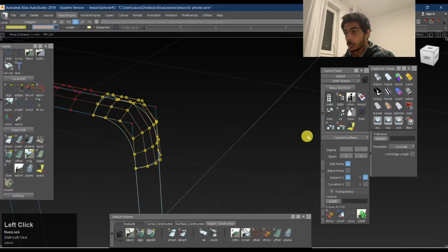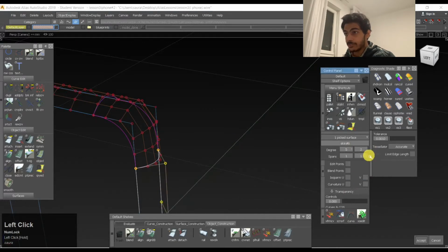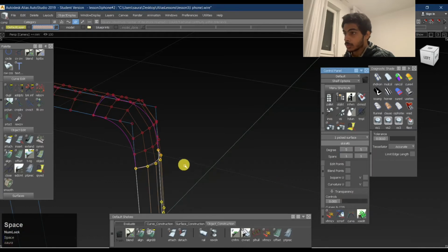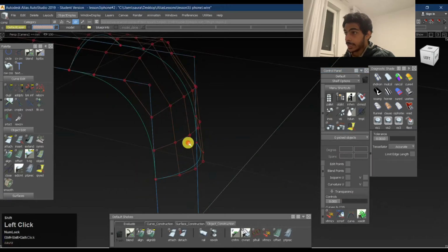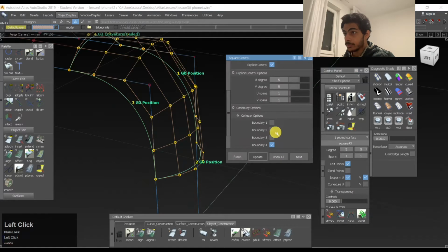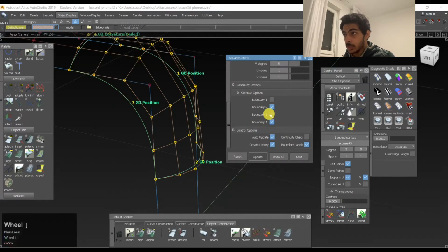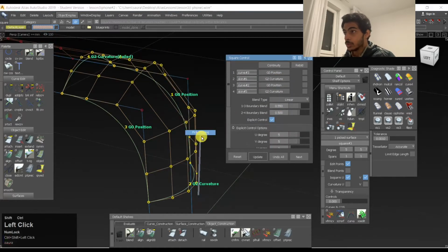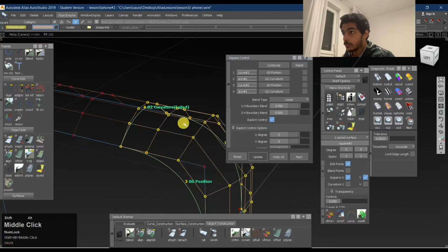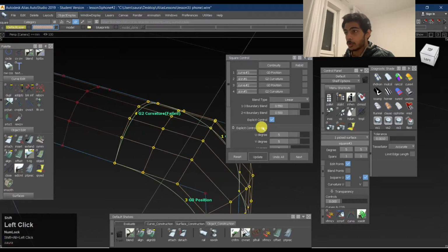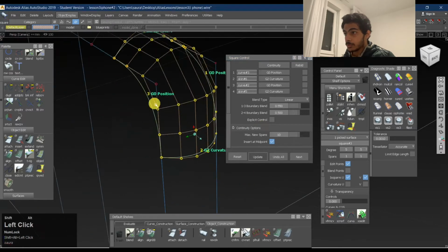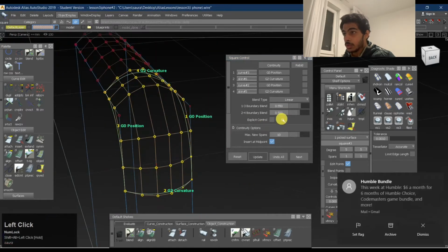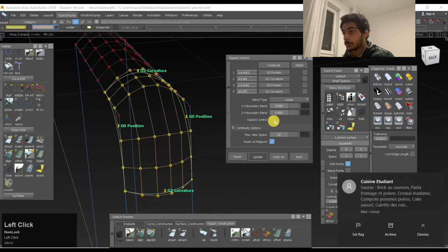The same thing we'll do over here. This is 2 by 2. We'll try to make it 5 by 5. And then again try to query edit history for this. Collinear with this. There's a collinear option over here. And in the second option, we'll just make it G2. You see, we are able to achieve G2 over here. We weren't able to achieve G2 over here because obviously, yeah. So sometimes it's better to switch off the explicit control option as well.